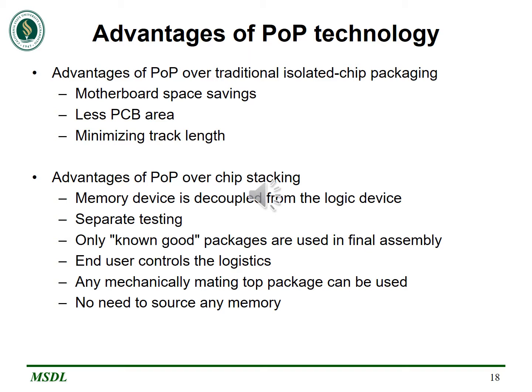This yields better electrical performance of devices since shorter routing of interconnection between circuits yields faster signal propagation and reduces noise and crosstalk. And another advantage of using this package on package semiconductor over chip stacking is that the memory package can be tested separately from the logic package. Only known good packages are used in final assembly. Compare this to stacked die packages, where the entire set is useless and rejected if either the memory or logic is bad. The end user controls the logistics.